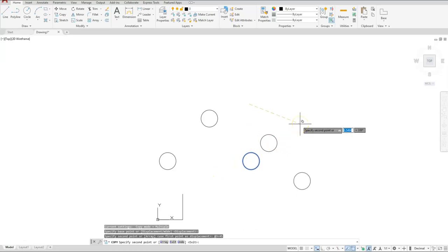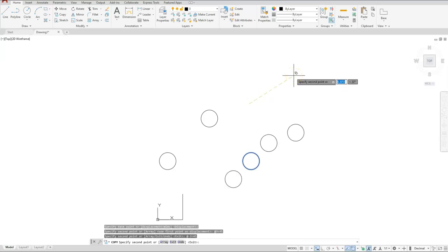Now, I was telling you before that we can also use negative numbers and also negative angles. So, for example, I'm still at this same copy point. Let's say I want to go -3, which is kind of saying, okay, I'm aiming this direction, but I want to go backwards this direction. Now, I'll demonstrate. So, if I'm going to type in -3 angle 45, you should be expecting to get a circle on the back side of it this way, because I'm pointing this direction but go a negative distance, and it did produce that.